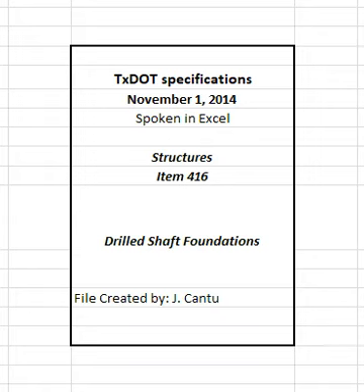Do not excavate a shaft within 2 shaft diameters, clear, of an open shaft excavation, or one in which concrete has been placed in the preceding 24 hours. Dispose of material excavated from shafts and not incorporated into the finished project in accordance with the plans and with federal, state, and local laws. Provide suitable access, lighting, and equipment for proper inspection of the completed excavation and checking the dimensions and alignment of shaft excavation.